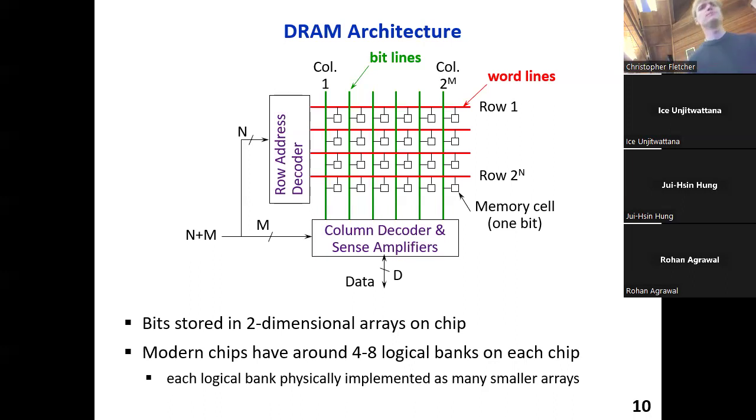Yeah, so typically this varies depending on how you've set up your machine. Some of this control you have in your BIOS, but there are two ways that a write can happen. The first way is there's a structure underneath the column decoders that we haven't talked about called the row buffer, which buffers the previous row that you've read or written from the DRAM. You can think of it as a one-word cache. So one way to do the write is if the data that you need is already contained in the row buffer, you just merge the write into the row buffer and you're done.